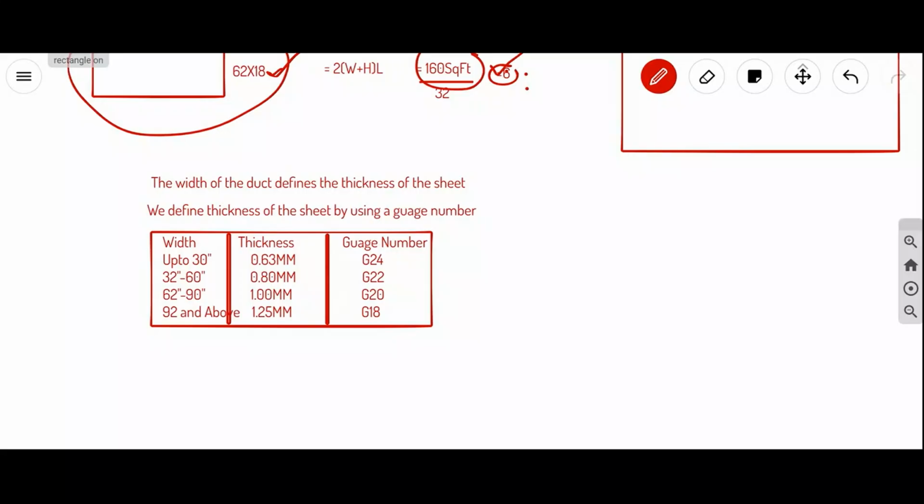Okay. So while creating the duct, next is insulation. So insulation thickness, every material has a different one, sir, but the standard recommended insulation thickness is 1 inch for the supply duct. For the supply duct, 1 inch; for the return duct, 2 inch.